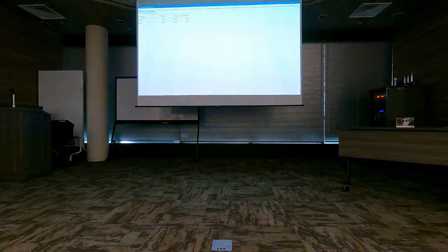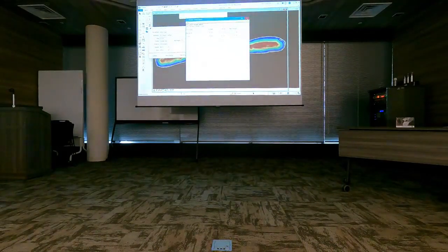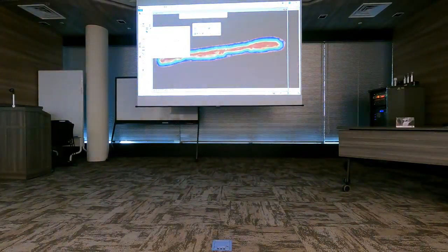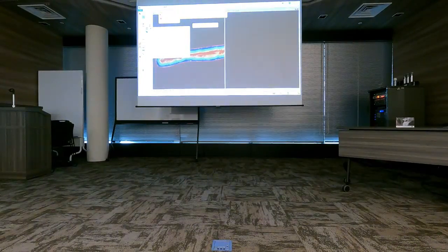As a result, a report of the file's volume is output. And I see the volume in cubic meters. I see the area computed in square meters, and I see the maximum height of the stockpile. The relevant data is included in the report. If I do something like this, it's a good idea to do a little bit of viewing to check what the software has computed.